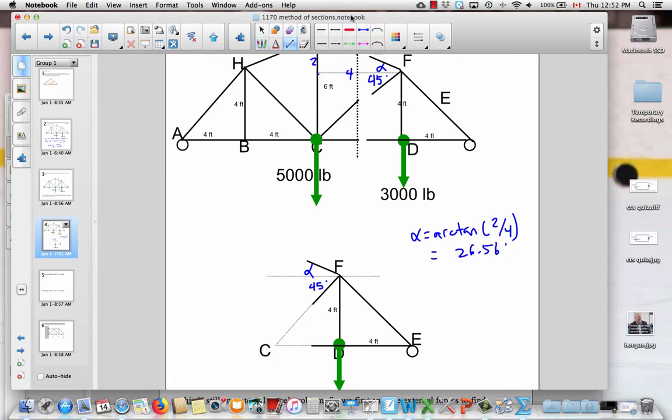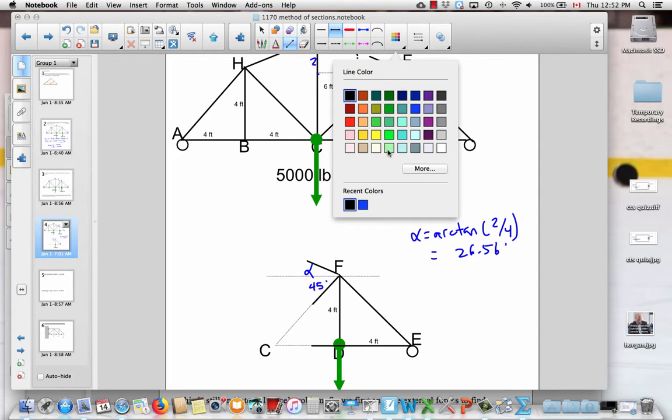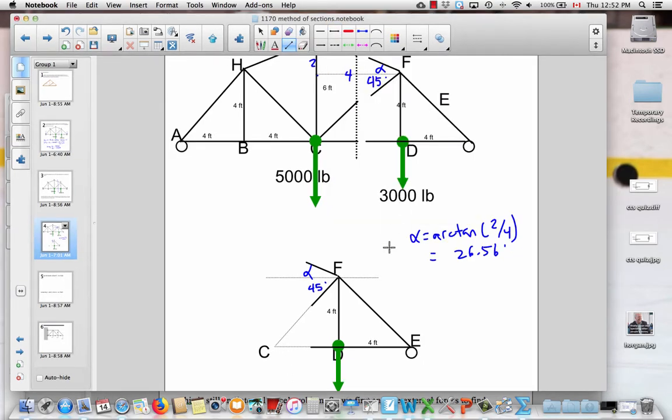And now, thinking about the forces, we will assume that they are in tension. Okay? And so that means that the other half of the structure is going to be pulling this way on the right half. So that'll be the amount of tensile force in the CD member. We'll be pulling on the right part of the structure along the CF member and also along the FG member. Now, these are two force members, so these forces are parallel to those structural elements.